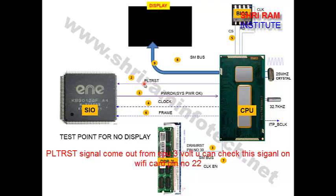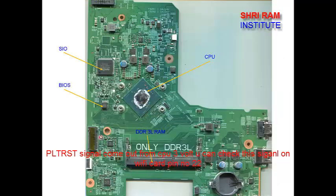This signal you can check on the Wi-Fi card. This one is a Wi-Fi card slot. You can check this signal on the Wi-Fi card pin number 22. At pin number 22 you will get 3 volt. If you get the 3 volt there, that means the CPU generated the PLT reset. That means all powers are okay, and the CPU generated the reset signal, which you can check on the Wi-Fi card pin number 22. Okay, and now the PLT reset is okay.